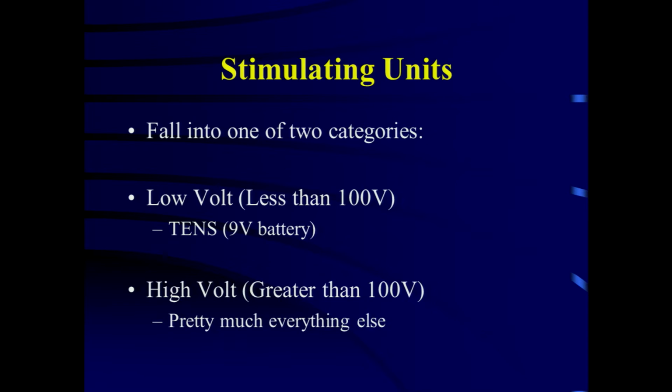But the more fundamental thing is this: if I draw V versus I, this is my voltage source. No matter what current is drawn, ideally it must maintain the same potential across the two terminals. On the other hand, for a current source, no matter what the potential across its terminals is, it maintains the same current.